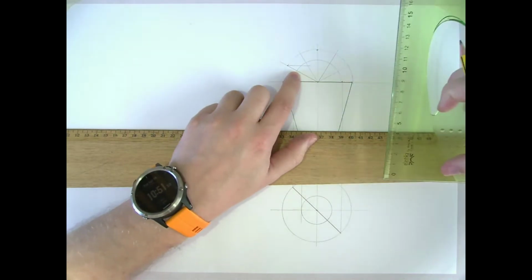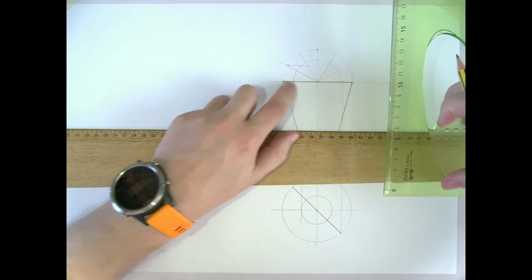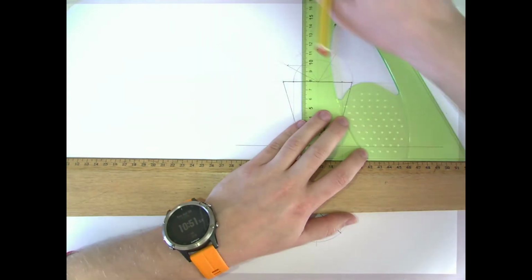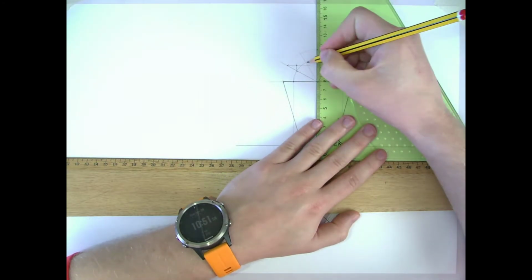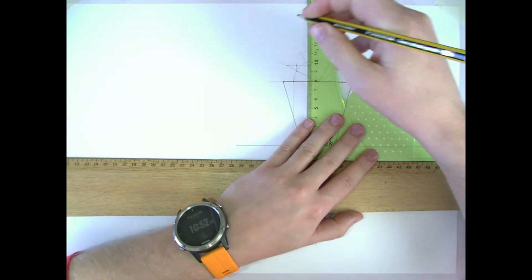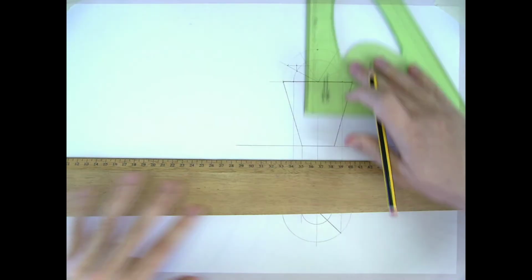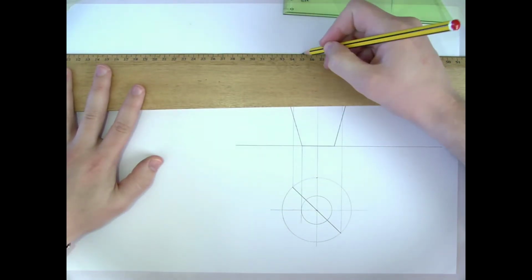That same line cuts the minor auxiliary circle here, so our minor axis is down here. So perpendicular to that is coming this way, giving me that point. Same for this one here, minor auxiliary circle, so perpendicular to the minor axis, perpendicular to the major axis.